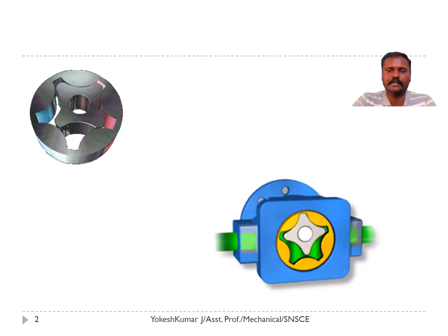Once it is directed to the left hand side, it will enter the outer ring gear. Here we can see the gap between the inner gear and the outer gear. The gap keeps on increasing to a certain limit, and then it reduces. When the oil pushes the inner pinion, it tends to rotate.